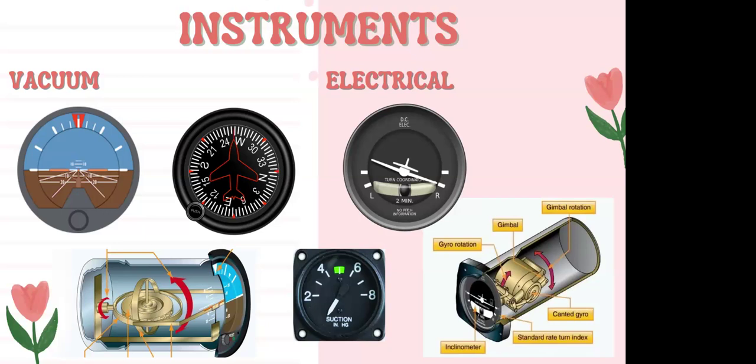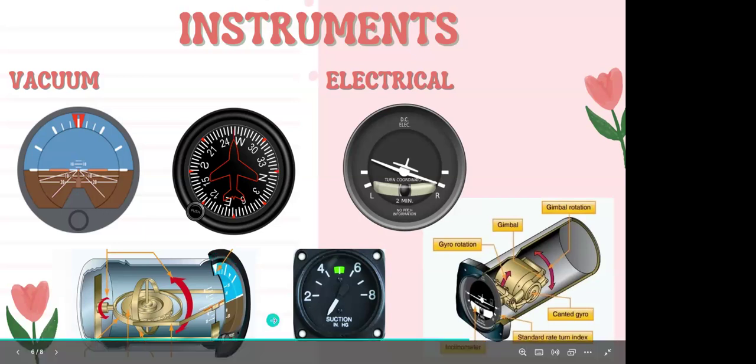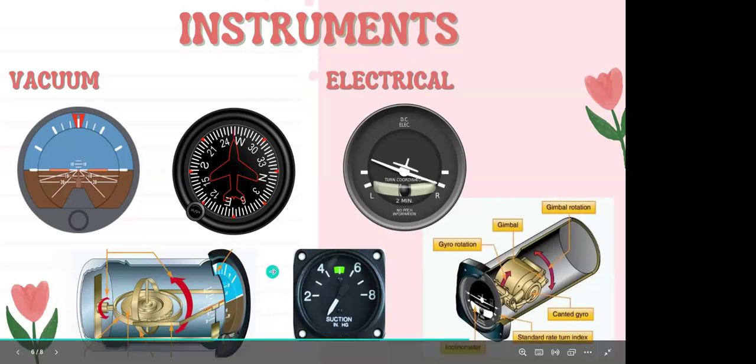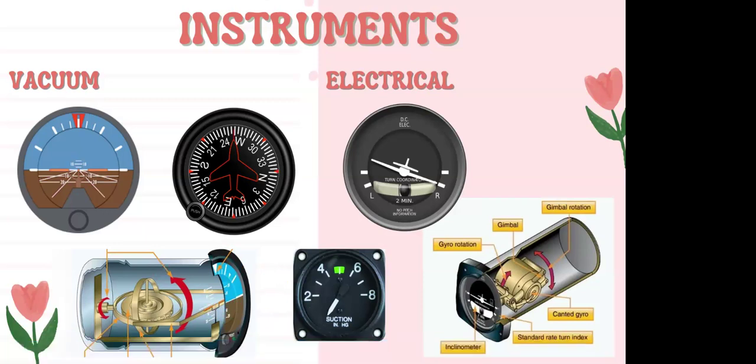So it'll kind of move with you. And there's some arms down here attached to the gyro that move the aircraft on the face, which is what you're seeing in the cockpit of the instrument, which will tell you your relative position to the false horizon. So 30 degrees of bank and 10 degrees of nose up, or whatever you're doing.